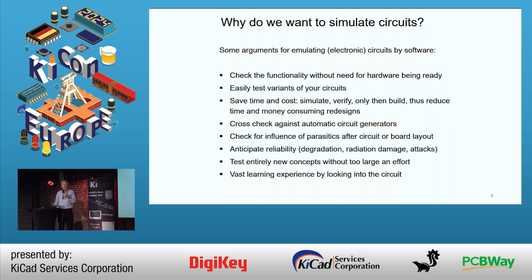You can anticipate reliability, so you can do degradation simulation, or even radiation or sidewall attacks to be simulated before they occur in reality. You can test entirely new concepts without too large an effort. And I think very important is also that it's a vast learning experience. You look into the circuit. You can have a look at each of the nodes, what is happening there, what the electrons and the voltages and the currents are doing.